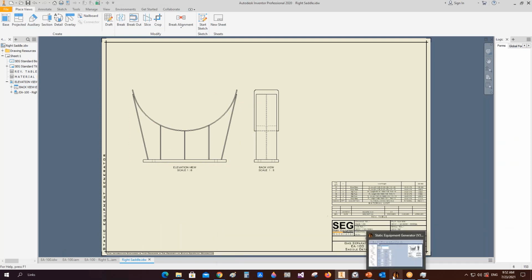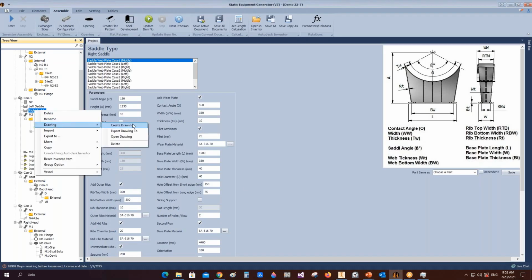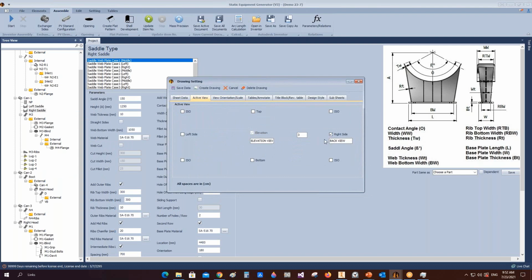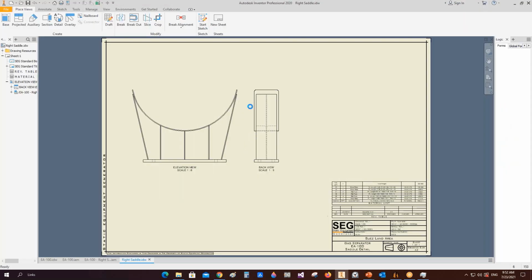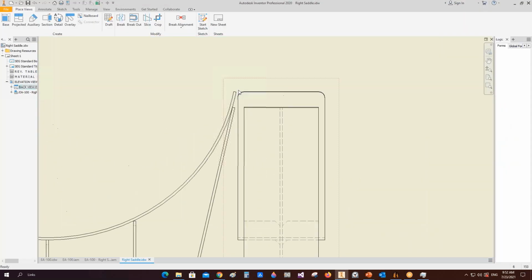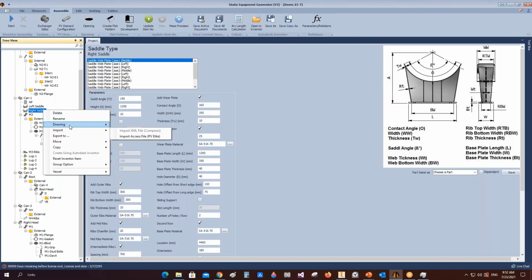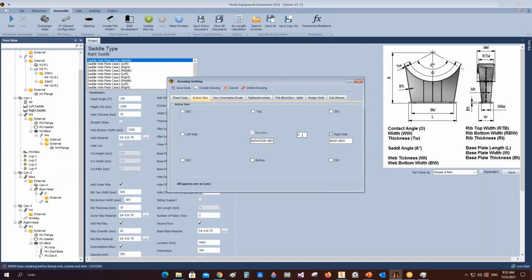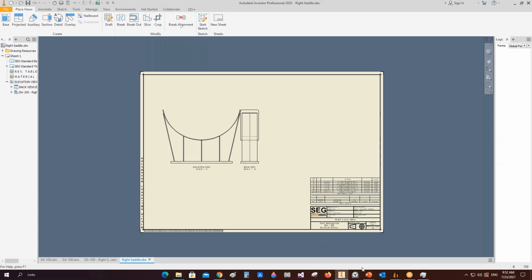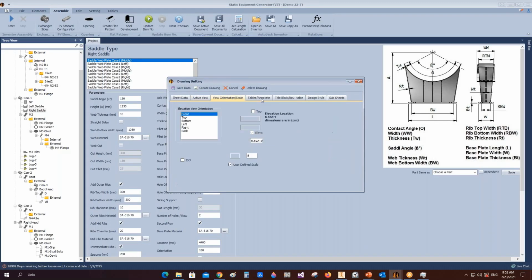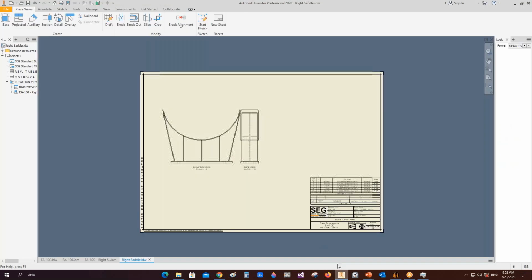The spacing between views, we can define it from this button here, the activate view, so you can control the spacing between views. So if we make it 0, for example, and click on create, those two views will be with 0 spacing between them. So if you would like to increase this spacing, you can define it from the activate view. Let's make it 6 and let's move it a little bit up. So from here, let's change the Y location to make it 28 and click create.